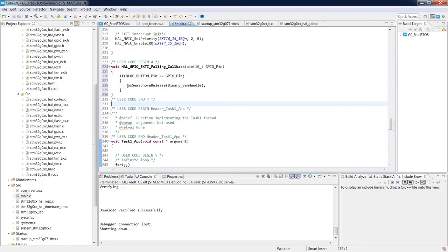One more thing on this point. Executing code within this callback is still done within the interrupt routine of the external interrupt from line 13. This is an important point because please remember that our hardware interrupts should not interfere with the operating system. The cooperation between hardware interrupts and operating system functions should be done in a careful way. The big advantage of this CMSIS layer is that the CMSIS library is taking care of selecting the proper function if we are calling the operating system function from the normal code or from the interrupt routines.